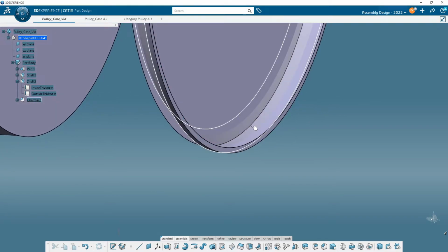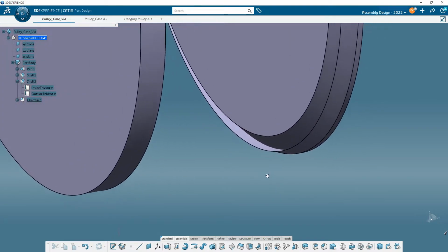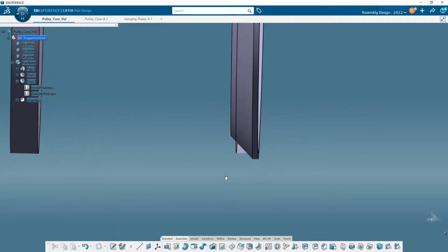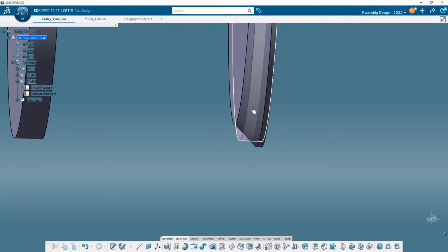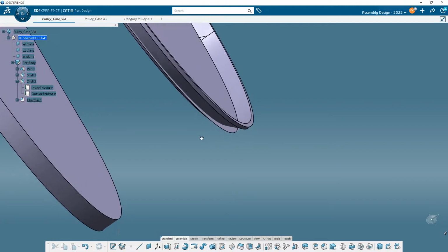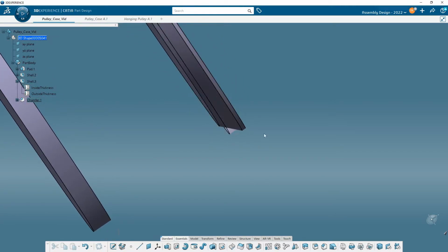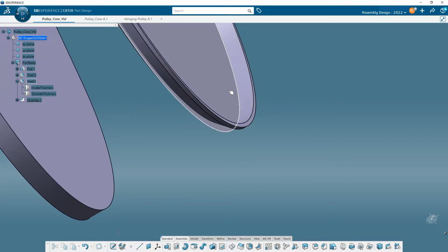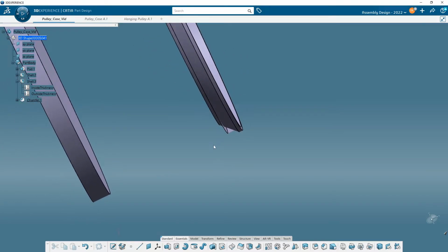So you see that this angle right here is sticking out past the chamfer. And if you think about that, you'll see why I'm saying that that's not possible. Other programs, you'll do this in Fusion 360, it'll actually leave a hole right here, usually, as far as I recall. So that's not good. So in order to get this to do what I need, I do the chamfer first, and then when I do the shell, remember I said it removes faces, but it leaves thickness behind on all the remaining. Then I'll have this nice little clean offset there.